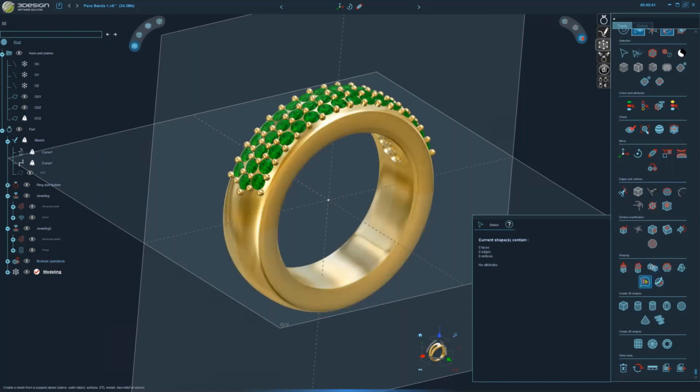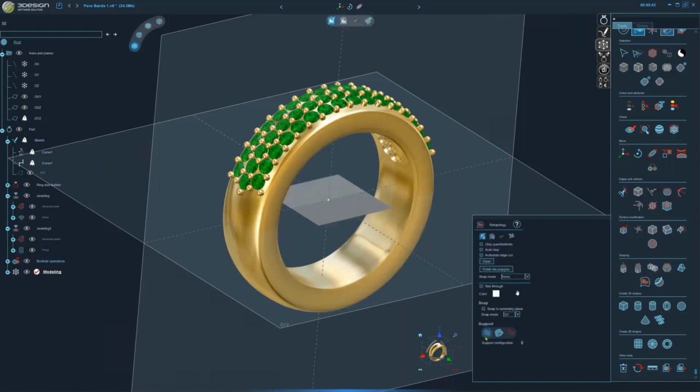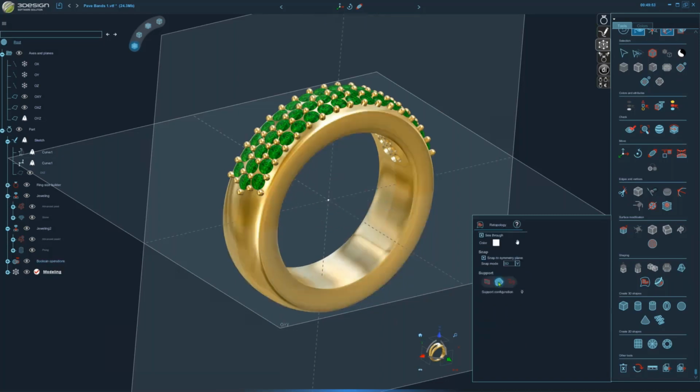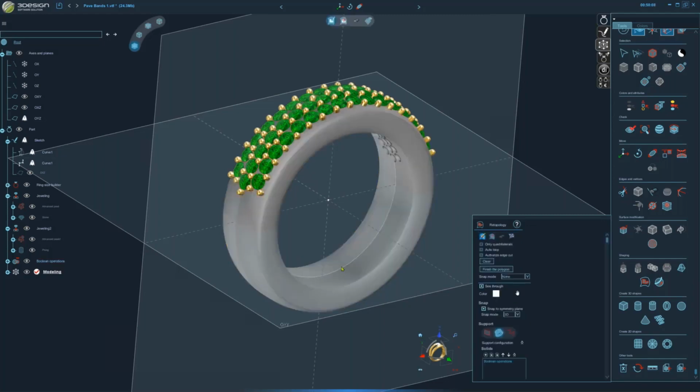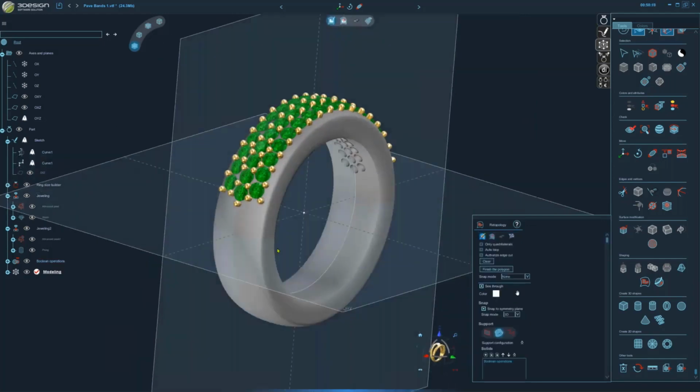So click on Retopo. Okay, and the support object by default is a plane here. So we can configure the plane size and just draw something flat. In this case, though, we want to use an object. So I'm going to switch over to the solid mode, click an object, and you have to open up the little settings menu before you can add your solid. So pull that menu down, and you see your list of solids. You can do more than one, but we're just going to add the ring as our anchor item. Everything's going to snap to that.